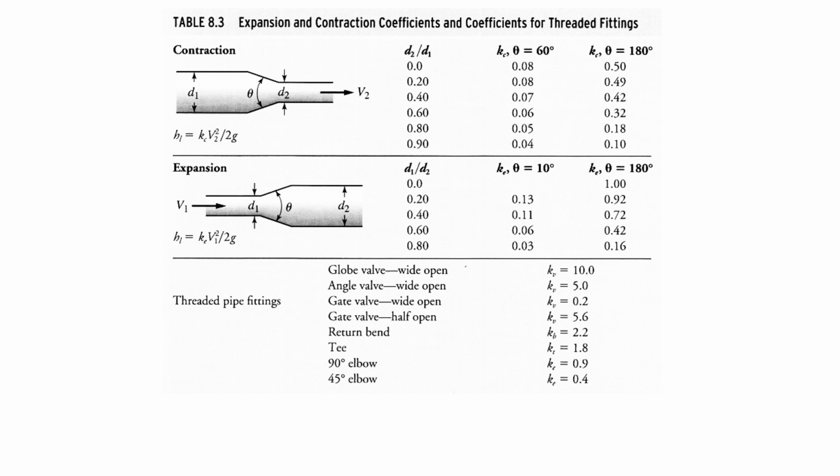That you have a large pipe that's feeding down into a small pipe, and so the water is experiencing some eddies and countercurrent flow that's causing turbulence right there at the inlet before it's reorganizing itself into the smaller diameter pipe. And so there's a larger K value for a situation like that than if it had been tapered and more gradual. And then the larger the difference in the pipe diameters, the bigger the K value as well.